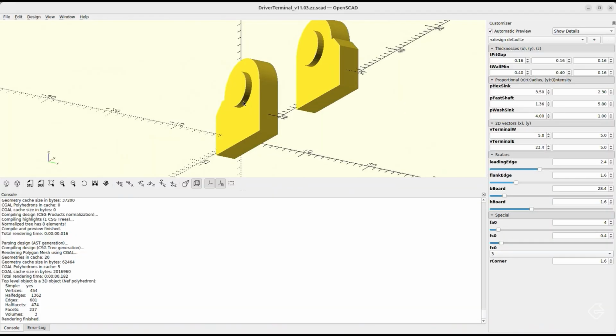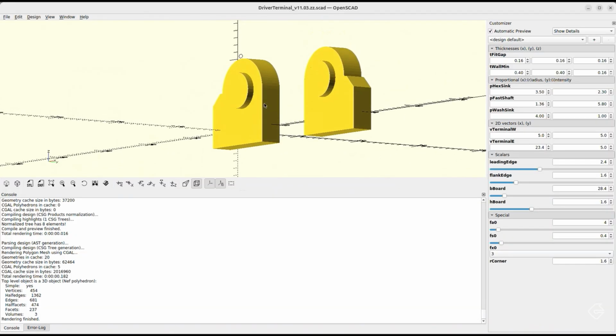of that hole. Now you may have noticed when we make those little extensions, we're actually creating a portion of this model that's going to be quite difficult for our 3D printer to print. See, the overhangs of this extension right here will be a great challenge for our printer. Now, we will need to do something about that, but we don't have the skills to do it elegantly yet. So we might cover that when we cover the more extreme advanced techniques in the next episode. So hold off until then. For now, we'll just move on.